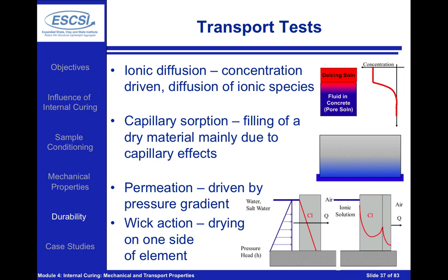Capillary sorption is the next mechanism, and this is really the filling in of the pores inside of a porous media or inside of our concrete by water absorption. This is a very fast mechanism and can really be looked at here as water being sucked up into the concrete.